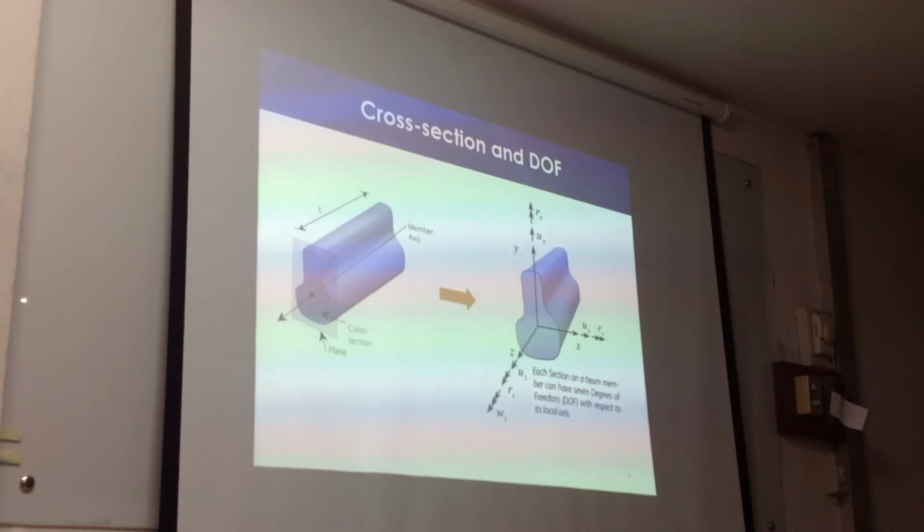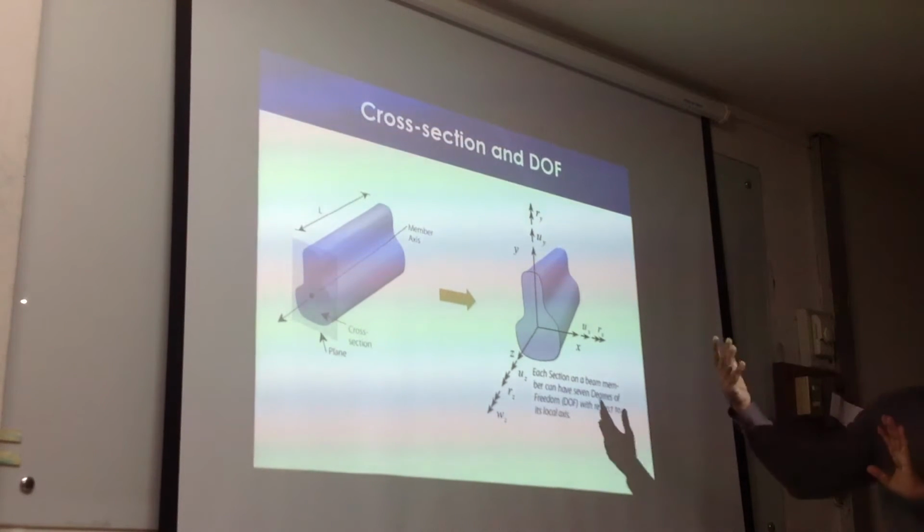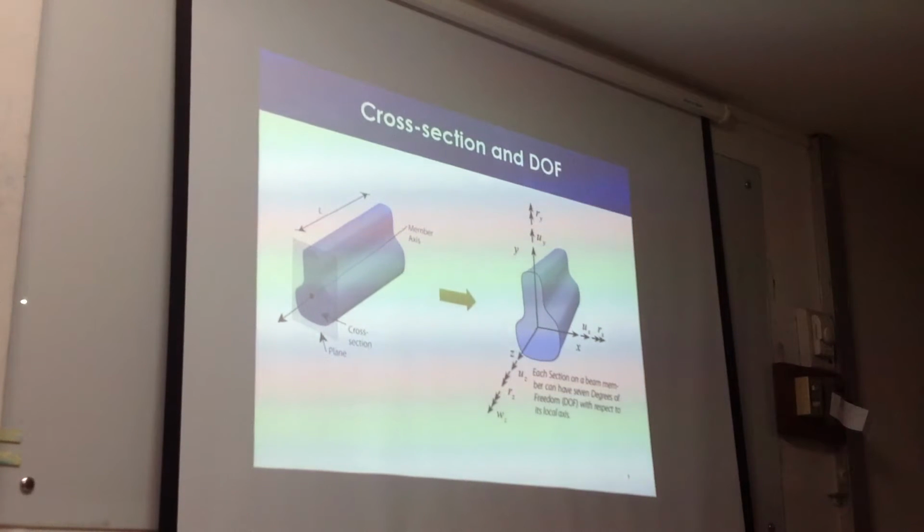Steel open sections like high sections are so flexible that they warp a lot, so much that it just distorts the cross section but does not produce large stresses because the stiffness is too small. Stiffness and stresses are related. If the stiffness is too small, you get large deformation, small stiffness, still no stresses. Understand the point? So we can ignore the warping in two extreme cases, but there are a lot of cases where warping is extremely important.